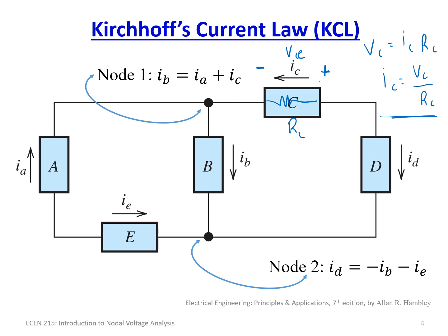So again, let's do element A. Let's pretend this is a resistor, and we're going to give it resistance RA. And then we're going to call it this plus and this minus, again using the direction of the arrow as our guide here. Then IA is equal to VA, and VA being defined as this positive and this negative, over RA. So it's very important that you make sure that the arrows and the plus and minuses agree, else you're going to get things backwards and your math is not going to balance.